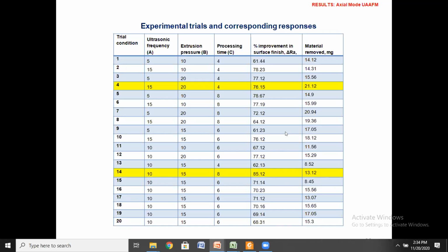Since it is a surface finishing process, you have to give top priority to percentage improvement. However, in other processes, if both responses are important, then you have to go for multi-objective optimization. In that study, you will go for either a minimization function or a maximization function, and you can get the exact optimum values. You can get the A, B, C optimum for maximization of surface finish and maximization of MRR. That particular set you will not get from the RSM, right?